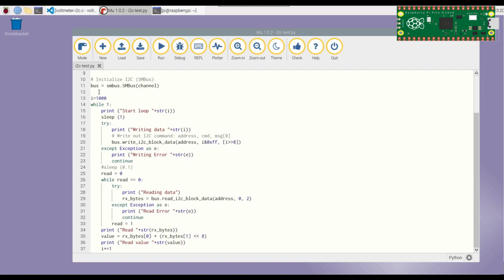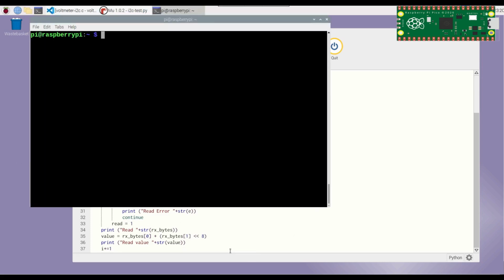So that's the Python code, and now we can give a quick demonstration of this working. I've set up UART debugging so I can use minicom on here. I'll use the options -B for baud rate 115200, -O to force it, and the device that we've got it connected to is serial port 0 on the Raspberry Pi. I've explained that in my previous video if you want to see more detail.